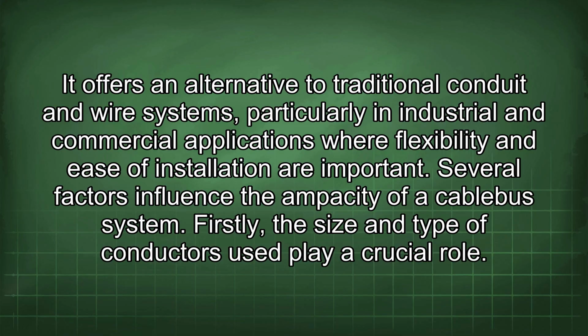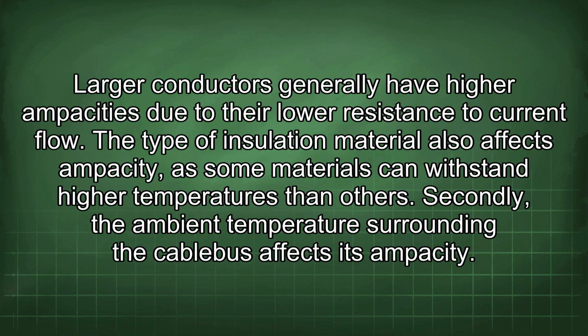Firstly, the size and type of conductors used play a crucial role. Larger conductors generally have higher ampacities due to their lower resistance to current flow. The type of insulation material also affects ampacity, as some materials can withstand higher temperatures than others.